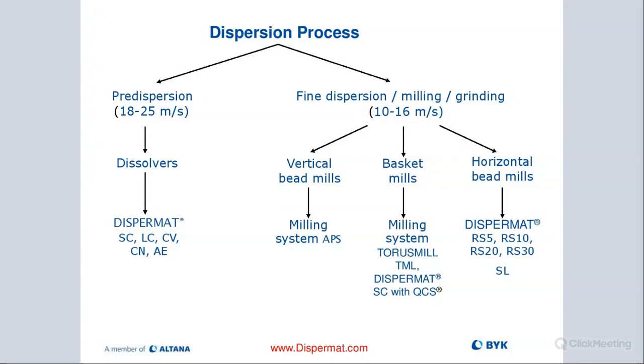That would be with a rotor, and probably you need a high quality ceramic rotor. We have zirconium oxide, white, and also high quality beads, and then change the screen on the nanomill after so often. To get to the smallest particle sizes, like 50 nanometers and below, you really need to use super fine media. It's going to take quite a long time, but it's definitely possible, and with our equipment we can do it in the lab as well as in manufacturing.